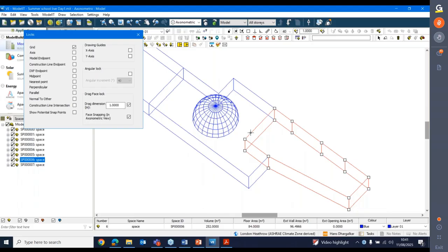Okay, so you can put holes in internal ceilings and internal partitions. But you have to draw the rooms first, and then afterwards you put windows or doors and holes in. And we'll do that later on. Okay, so that's a key thing to remember. Only draw holes in internal partitions, otherwise your thermal software won't be allowed to simulate.